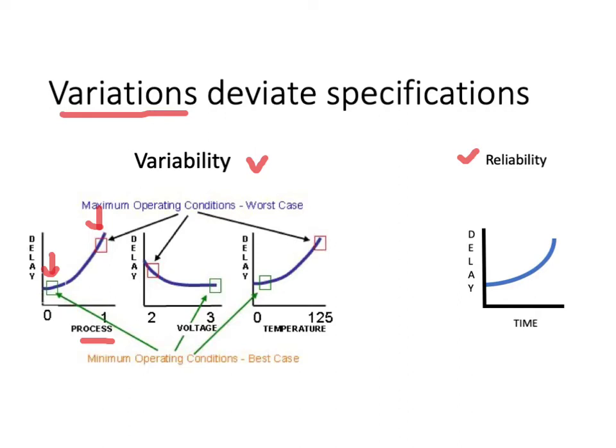The transistors are switching on and off very rapidly, and these switching transients will actually induce inductive voltage drops across long wires, and they also might be due to IR drops, resistive drops over long wires. These transient changes in voltage may also affect the delay. So if the voltage is on the higher side, then of course transistors are a little bit faster, because a higher voltage gives more current, and more current is more drive strength, so the transistors can actually charge and discharge quicker.